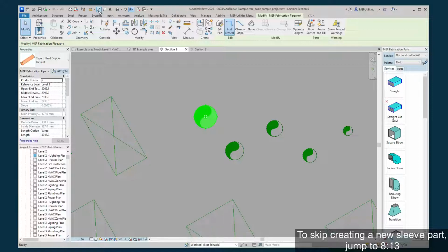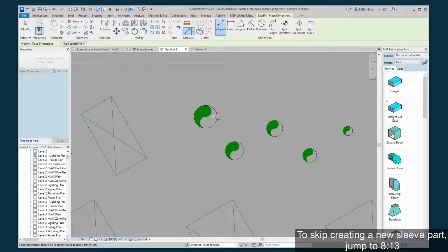What you can do is figure out the overall outer diameter, which for this pipe is 130. So you'll probably want a sleeve that's a little bit larger than 130, so maybe like 131 in this case, so that when the program looks at this part, it'll see 130. It will see that the sleeve is larger than this pipe, which means it can use that sleeve for it.